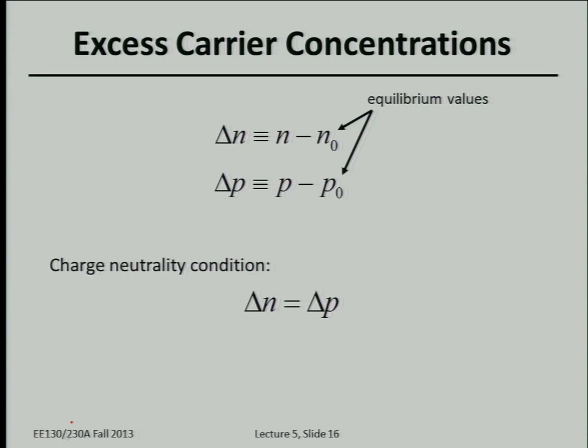Okay, so right now let's think about our carrier concentration affected by those excess carriers. Previously, in the previous lectures, we spent most of our effort on analyzing the two terms, that's at equilibrium state, the carrier concentration for electrons and for holes. Right now, no matter whether I bring in recombination as well as generation, I always tend to disturb my equilibrium carrier concentration, right?